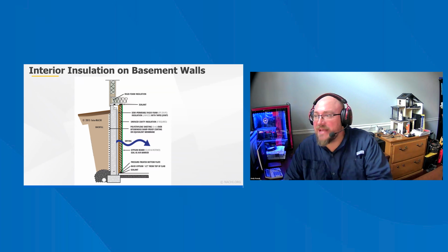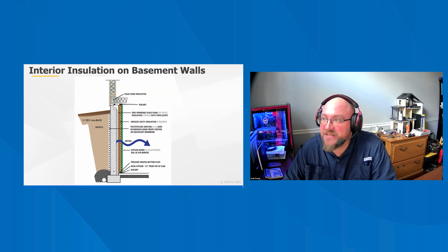This technique, as well as traditional basement finish practices, is not intended to compensate for inadequate waterproofing, foundation drainage, indoor relative humidity control, or air leakage control. If there are problems with water intrusion, drainage, humidity, air, or leakage, then the method of insulating the basement foundation wall will not matter. Insulating a basement on the interior side of the foundation wall is relatively new to residential construction as a best practice. Therefore, this strategy is included here primarily for your consideration.